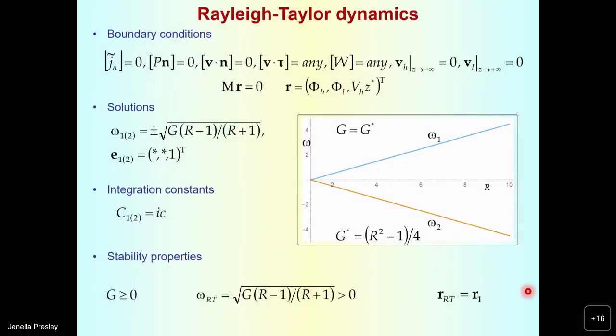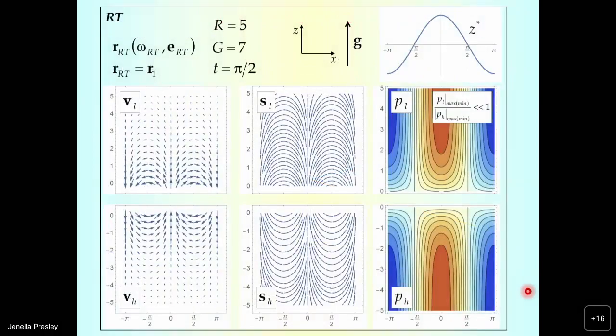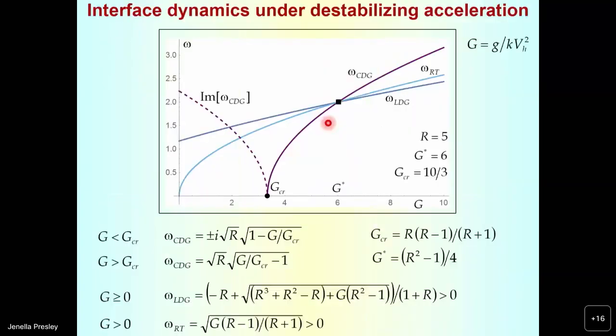We have stable and unstable modes here, and again, a situation for the flow fields. I would like to point your attention, even though quite often we keep in mind that our flow fields can be arbitrary, one can show precisely in Rayleigh-Taylor instabilities that the flow field should be potential in the bulk, and we might expect intense velocity shear at the interface as it's presented here, similarly to conservative dynamics.